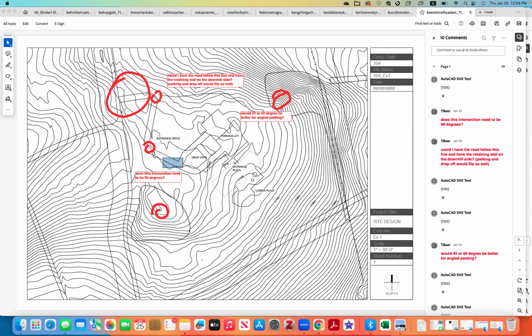The principles, for instance, being that we avoid having an entry drive over really steep, like over 14%. That's sort of a no-no because there are a lot of compromises once you get to 14%. If we have a better alternative, we place that as a higher priority than creating a special experience.